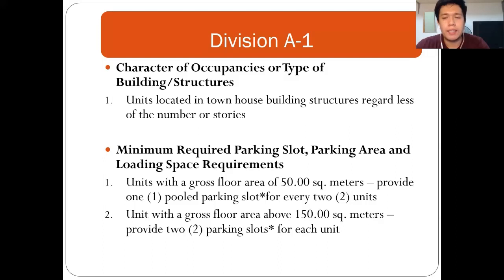Units located in townhouse building structures regardless of the number of stories. Units with a gross floor area of 50 square meters must provide one pooled parking slot for every 2 units. Units with a gross floor area above 150 square meters must provide 2 parking slots for each unit.